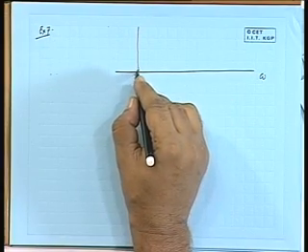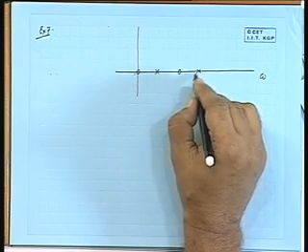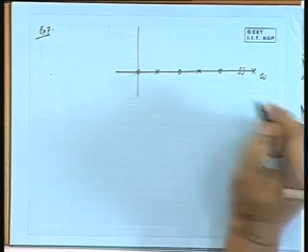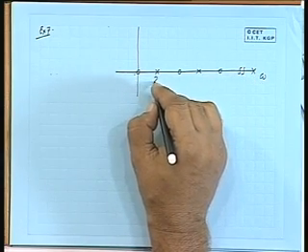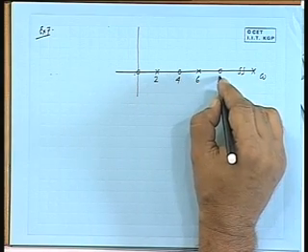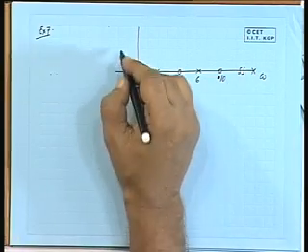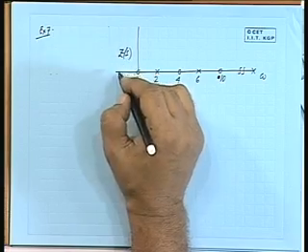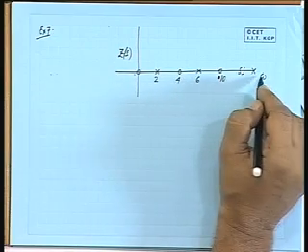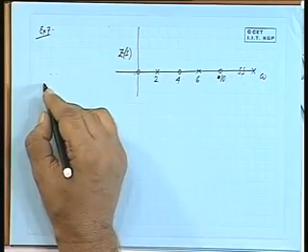This is a 0, a pole, a 0, a pole, a 0 and a pole. Okay, so this is 2, this is 4, this is 6, this is 10. Can you write the network function? Suppose this is for Zs. An LC function is having poles and zeros at these frequencies. What will be Zs like?